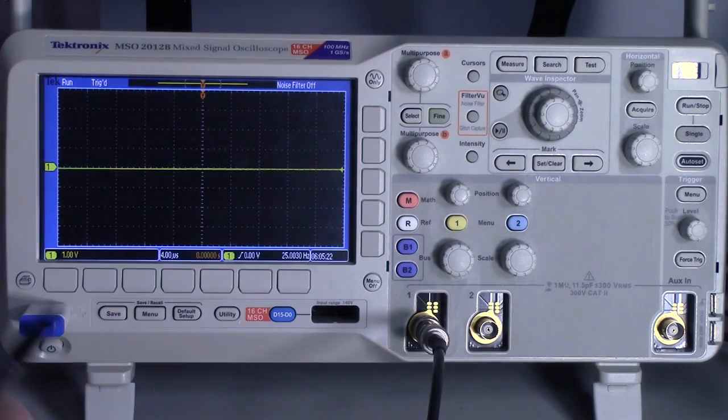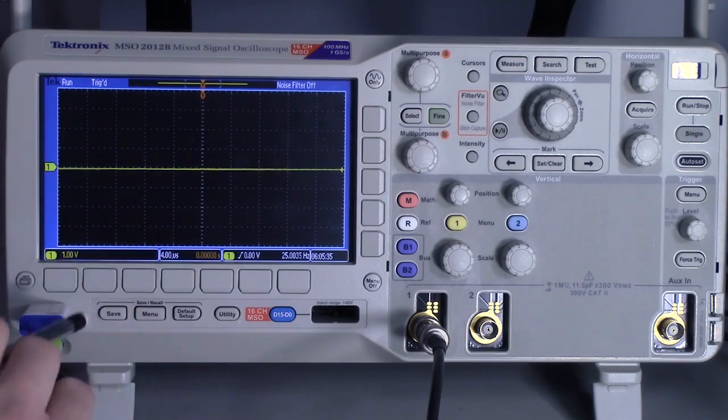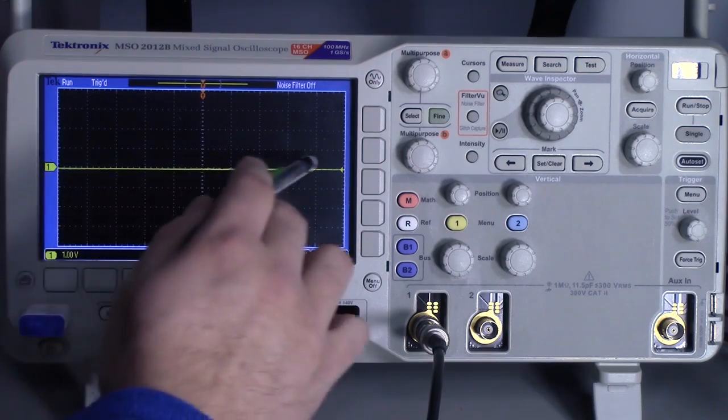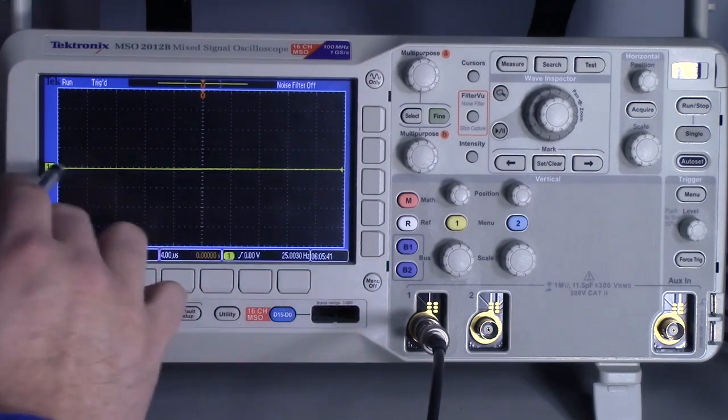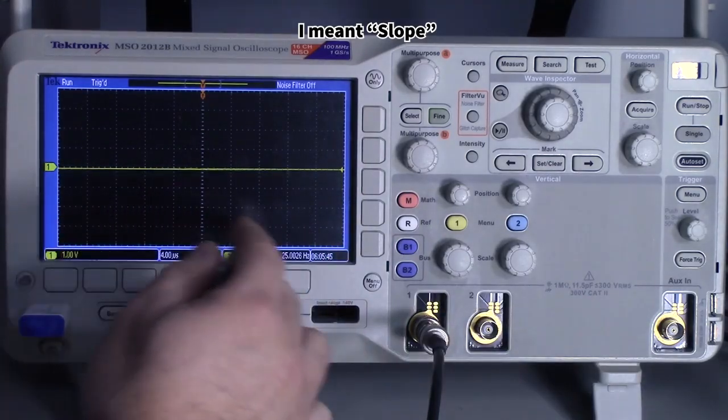So just click that. So now it looks like there isn't any information, but we can see the time scale is 4 microseconds. Before it was, I think, in the milliseconds. I'm only passing a 25 hertz sine wave to it. So you can see there's a little bit of a vertical scale to it. So I want to change the vertical scale.